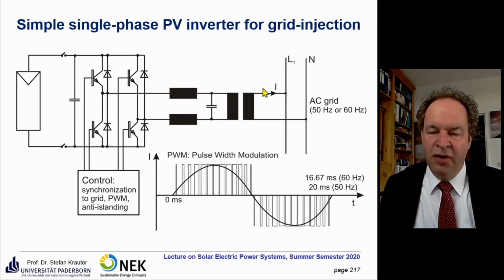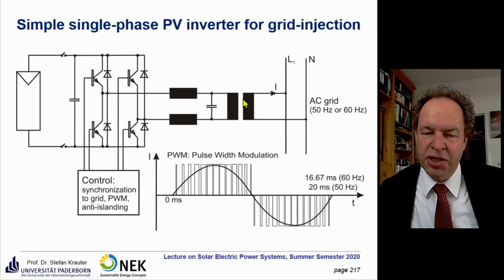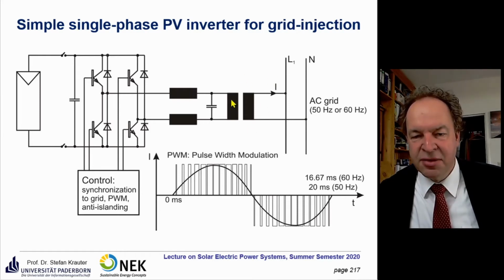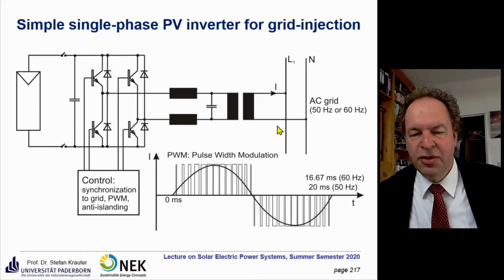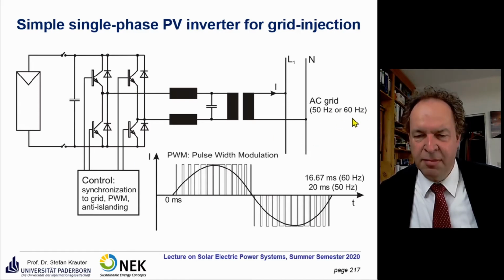And here you have a transformer; depending on the voltage that you apply here, you feed into the grid. While this transformer is quite costly, during the last years it was substituted, so they work directly with connection to the grid, so-called transformer-less configurations, or they create high frequency here, and then instead of using a large heavy iron transformer, you can use a ferrite transformer, which is really small and less costly than a big transformer. But then you have to transform that high frequency AC into DC again, and then it's transformed later at the right voltage into the 50 Hertz grid-compatible frequency, and synchronized to the grid. Depends, sure: in Europe and Asia it's 50 Hertz, Africa too, only the Americas have 60 Hertz. Also the north part of Japan has 60 Hertz.